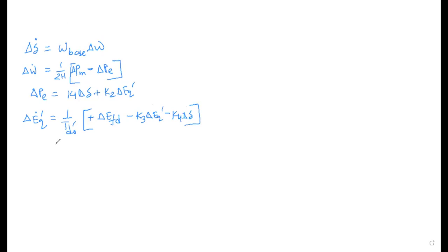And then we said we have an exciter. And now this exciter has some additional input in the form of UPSS. So this is basically the output of your PSS. Here you have del VREF, and this is plus, and this is minus del VT.